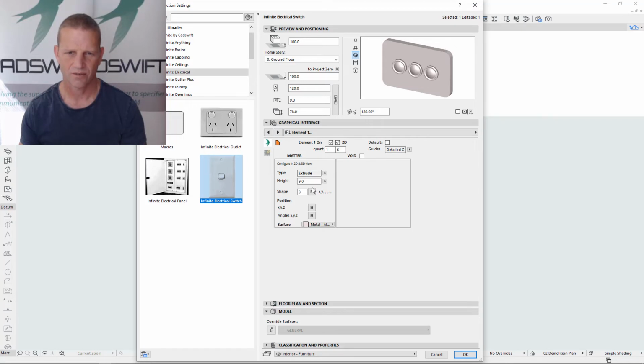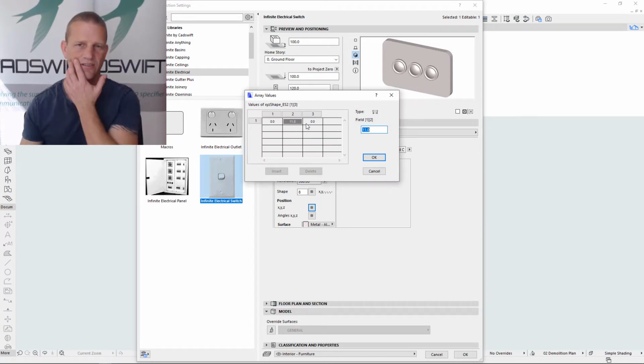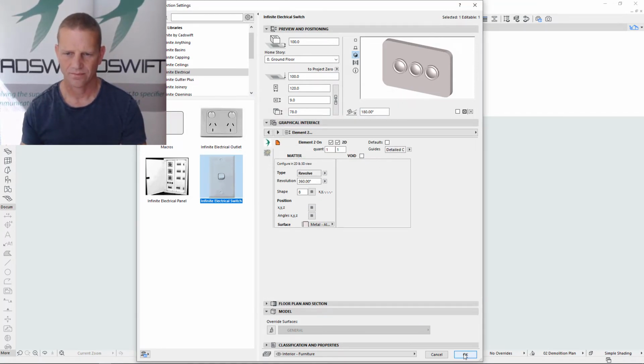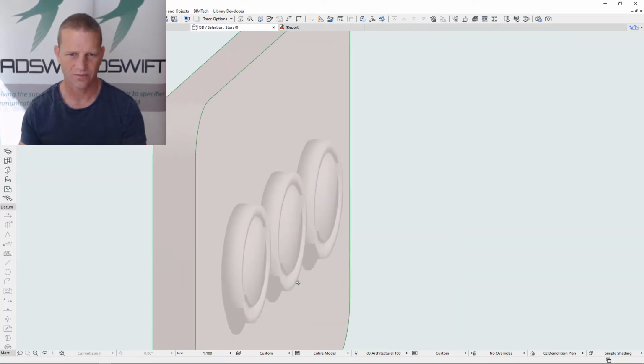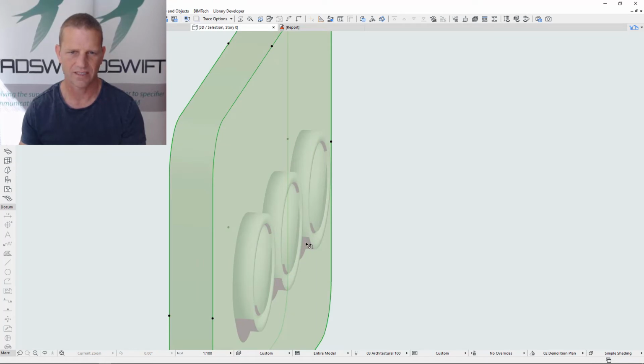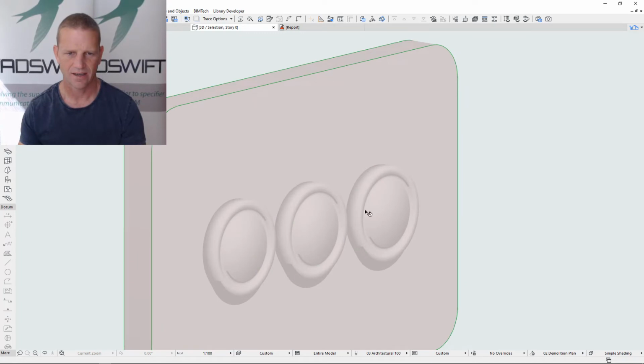Go back to the first element, we can see the height of that is 9, so Z position, Y position in this regard because everything's rotated, so that can be 9. Click OK. Now that's not a really flat surface touch button sort of scenario, so that would probably need to be recessed even further, and maybe even an extrusion cut out of this shape so that they stand out nicely within the shape.